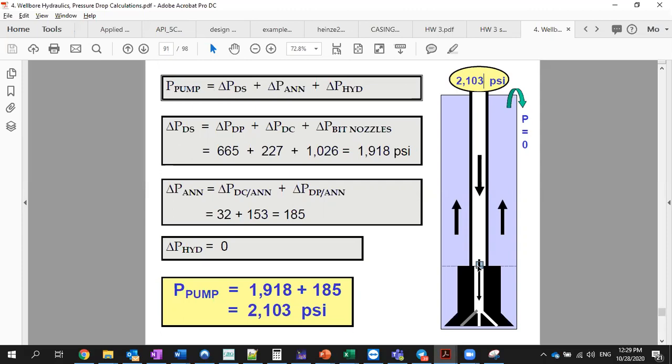Hydrostatic, right? Depth change. There are static properties, static pressure change, and there is a dynamic pressure change. So the static one is hydrostatic, right? How much it has changed from the surface to that point. Is it increased or decreased? Increased, exactly. So increased by how much? By 0.052 multiplied by the depth multiplied by the density, right?